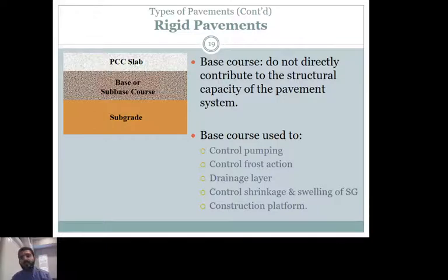It's much better for pumping concrete while having the reinforcement in place. If the reinforcement or the rebars are not attached well to a base layer, and I decide not to have a base layer and attach this reinforcement into the soil itself, once I pump in concrete, sometimes those reinforcements will move. So contractors like to have a base layer to have a good base for the rebars before we pump in concrete.